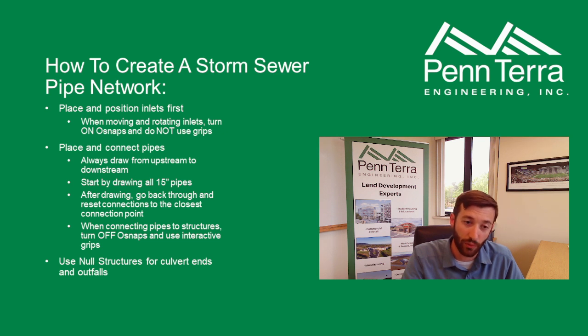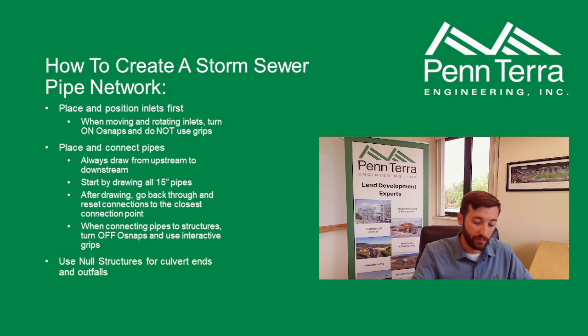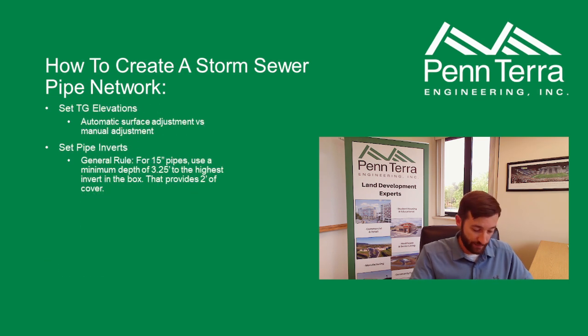And then another important point, when you're connecting pipes to the structures, you want to turn off your OSnaps, and the pipe networks will actually bring up interactive grips for where you want to connect them, and I'm going to show that as well. The other thing we do for culvert ends, outfall pipes, things like that, they have to have structures on the end so that you can show them in the storm chart. And I would use null structures because they don't plot, but you can still add a label to them. So that's how we do that.